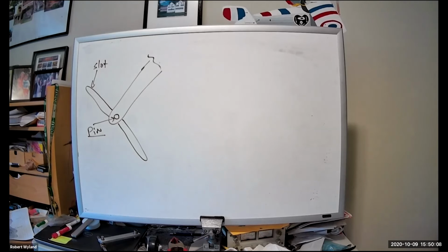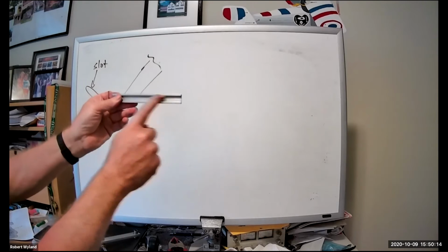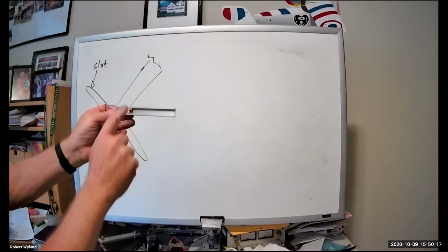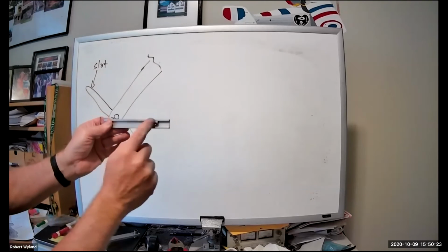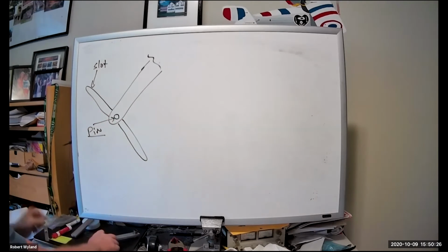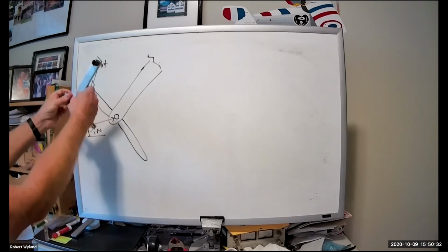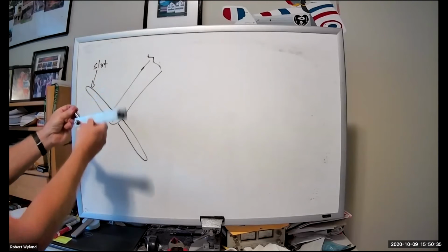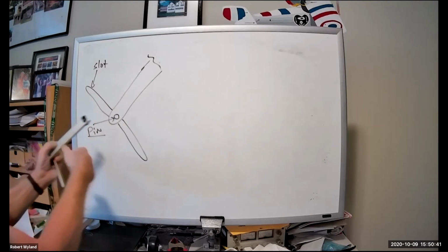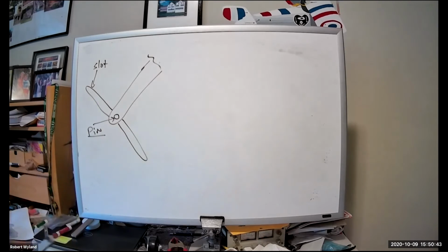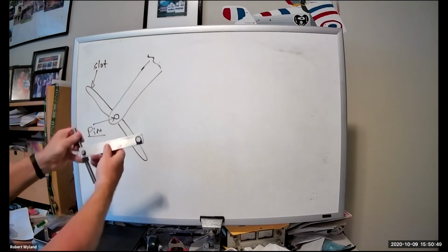So first of all, let's look at just here might be something that slides along inside, just a slide. And if I were to use this mounting hole as a pin, I could have something that rotates on there. And really what that looks like is this all over again. So we can slide along the slot and we can rotate this way, but we can't push perpendicular to the slot. And in fact, if you're off a little bit, they would slide along the slot. So we want to push directly on it.